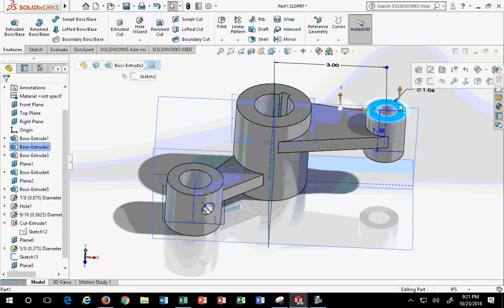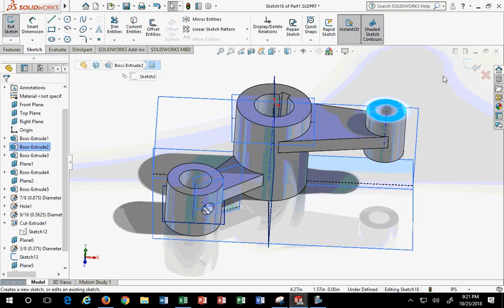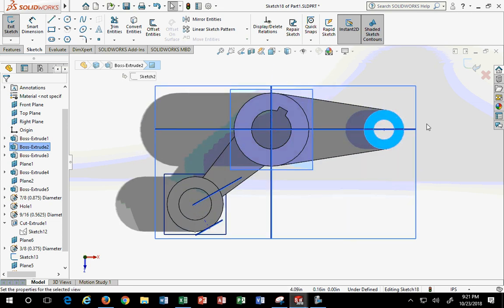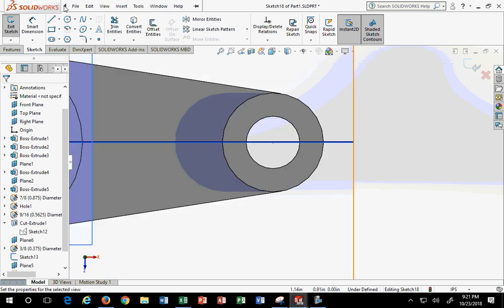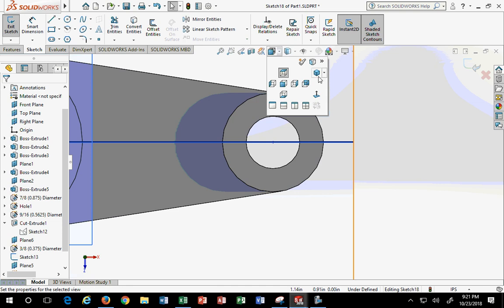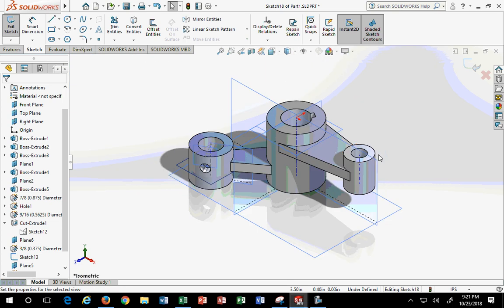Nope. I'll just go ahead and create a new sketch. Go normal to on that view. Yes, there's more than one way to jump to normal to. I'm using this method, but what's the other method? If I'm in isometric, I can do a Control 8.